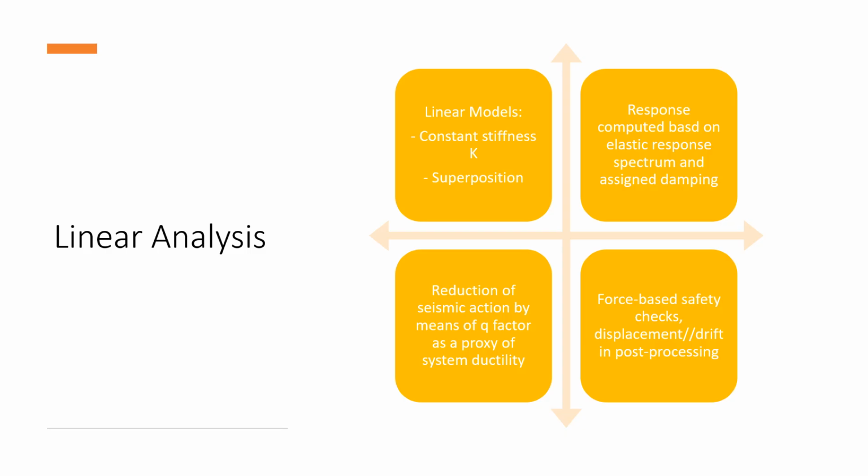And the response is computed based on the elastic response spectrum with an assigned damping specified for the family of structures we are considering, not specifically for the one we are analyzing.